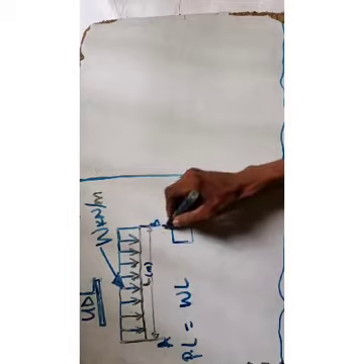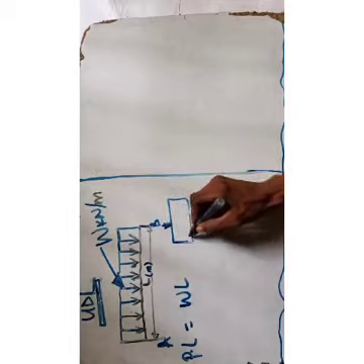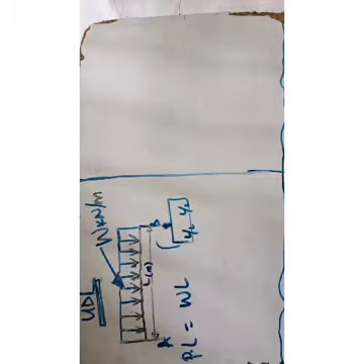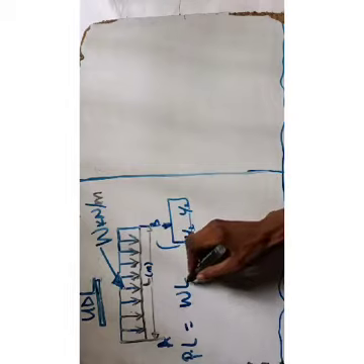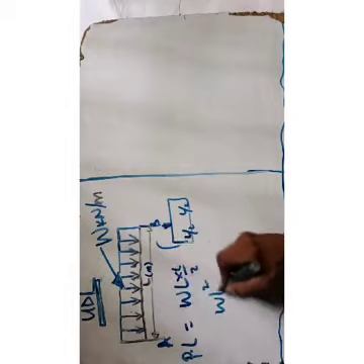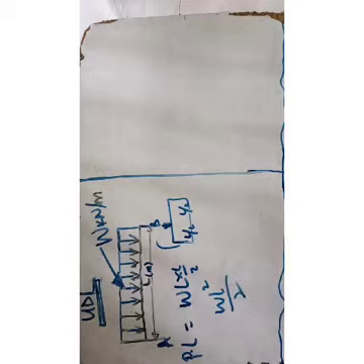The gravity will act at the center. Then, since the distance is L over 2, you can complete it by multiplying by the remaining half. Okay, that will be WL times L over 2. That will be WL square over 2. Now applying it to solve the question.